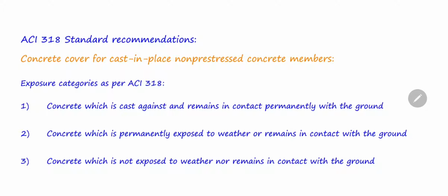If your local code doesn't give sufficient details about how much concrete cover should be provided to these rebars, then the recommendations of the American Concrete Institute may be adopted. The standard ACI 318 of the American Concrete Institute recommends the concrete covers for three exposure conditions.